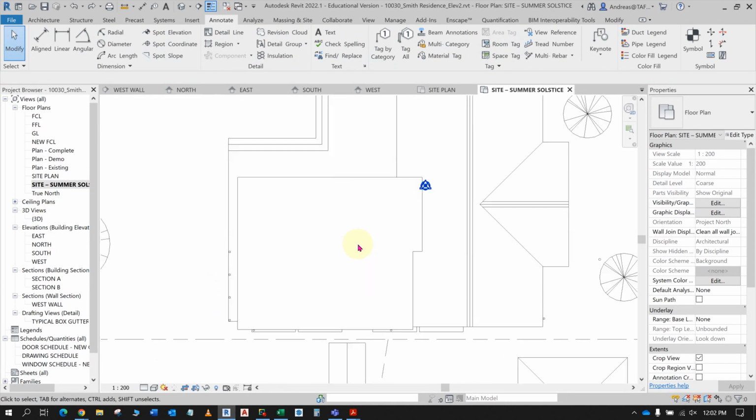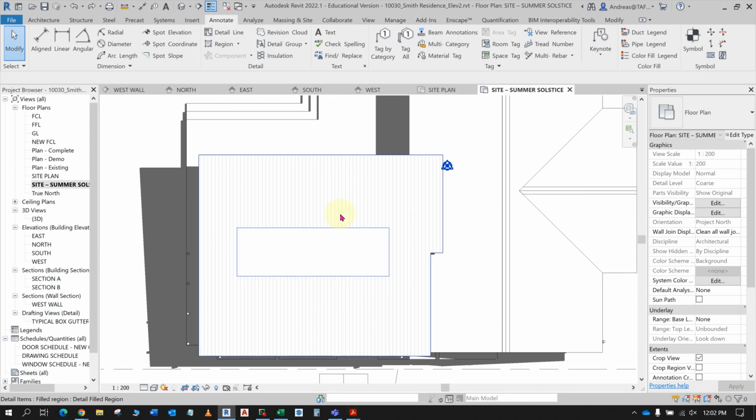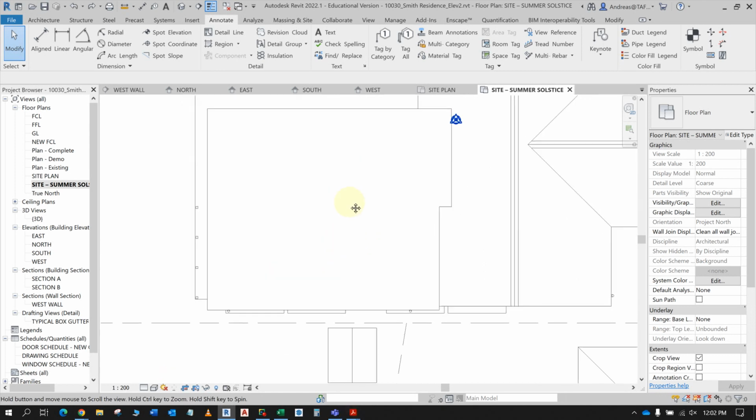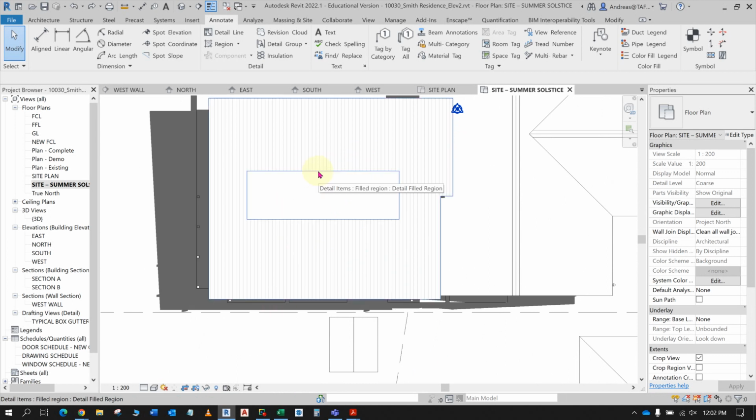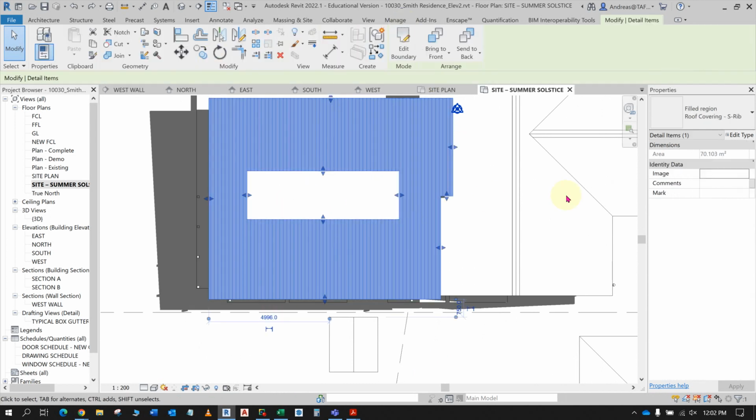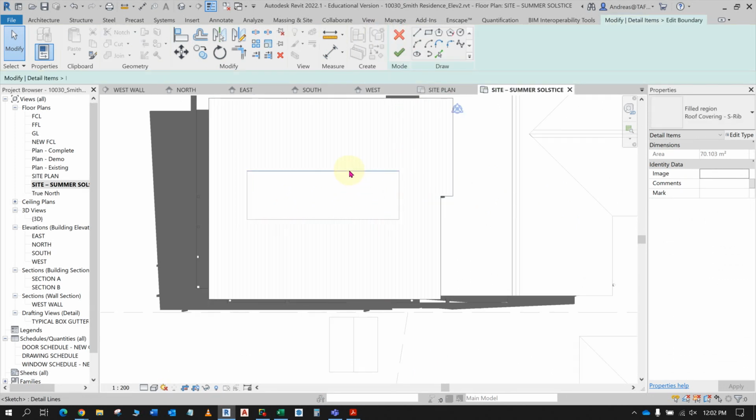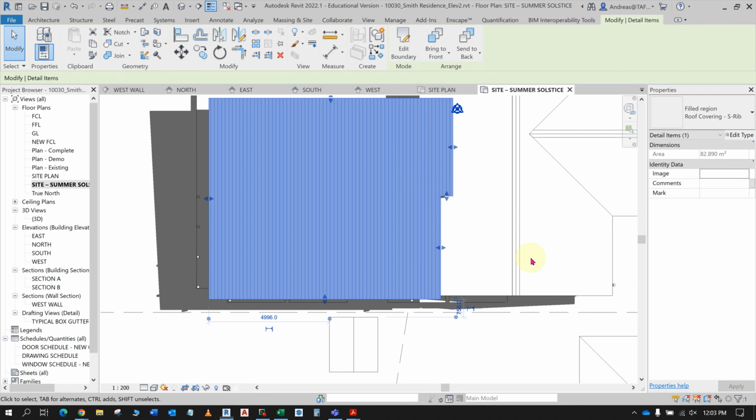All right, so I'm going to set this roof back to have a bit of a pattern through here. So we're just going to modify this pattern boundary and just edit the boundary here. So if you highlight it, you go edit on the ribbon. And what we do is chain select by highlighting that without clicking one of the lines and then tab and then left click, and then we'll just press the delete key. And if I go tick, it should just do that, right?